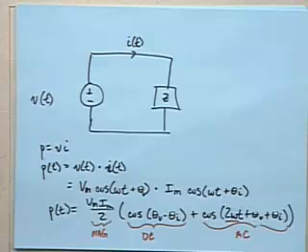It always catches me off guard to think that you've got this AC power, and we're trying to calculate as a function of time how you describe that power, and we've got a DC component and an AC component, and that AC component is at twice the frequency of its constituents, which is kind of interesting. But that's what the answer is going to be. You're going to get a function.